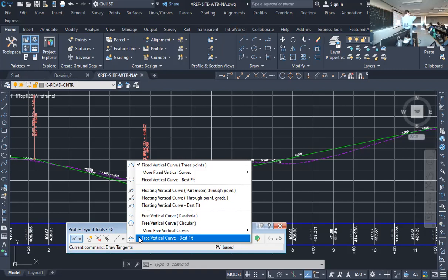It's a profile through the road. So if this was my road, cross sections would be looking in this way. Profile looks in along its whole length. So 0 is down here, and as you go up the road, if this is 1,000, this would be 1,000. That's what that graph represents: what the grades are doing along the center of the road. The first one was the existing, and what we're doing now is the design.